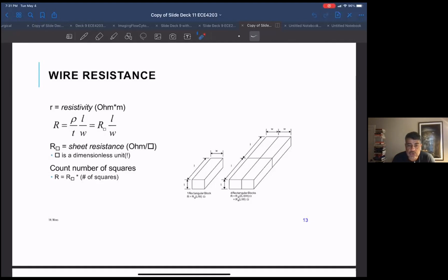Now, a warning: a lot of you are probably gonna do chip design where you're putting your chip onto some printed circuit board, and there the inductance is a very big part of the interconnect. At least in my experience, on a printed circuit board the copper wires are fairly thick and wide by on-chip standards, and copper has fairly low resistance.